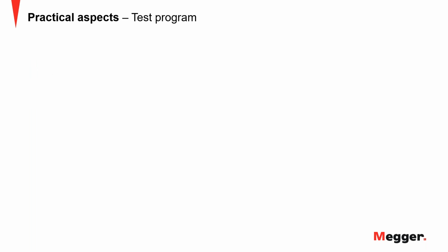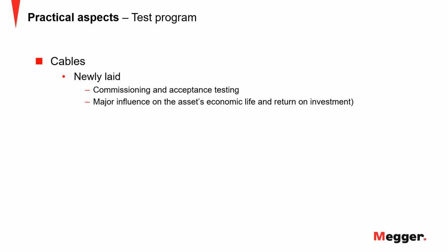So to the test program, again, talking about the cable itself. You can pretty much classify, you have new cable. That is its own application. New cable requires commissioning testing or acceptance testing, or in IEC, it's always the after laying test. That's their terminology for that.